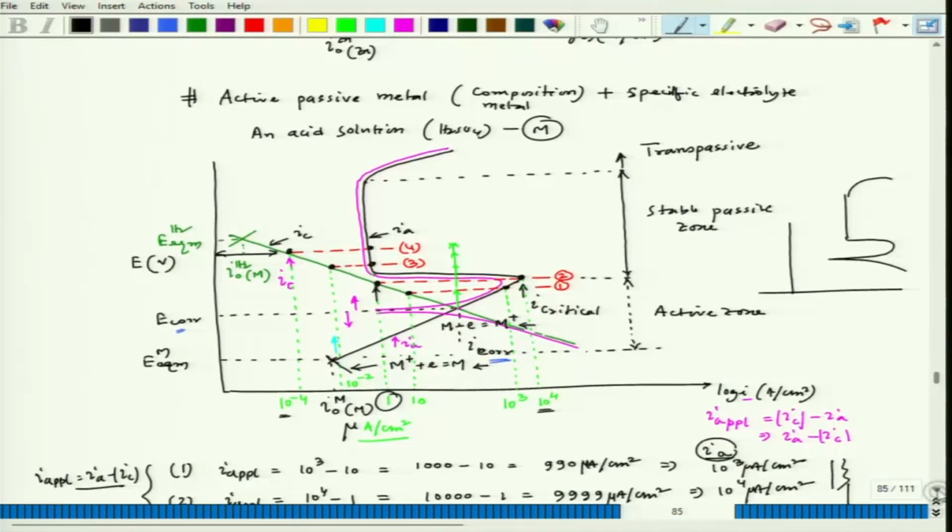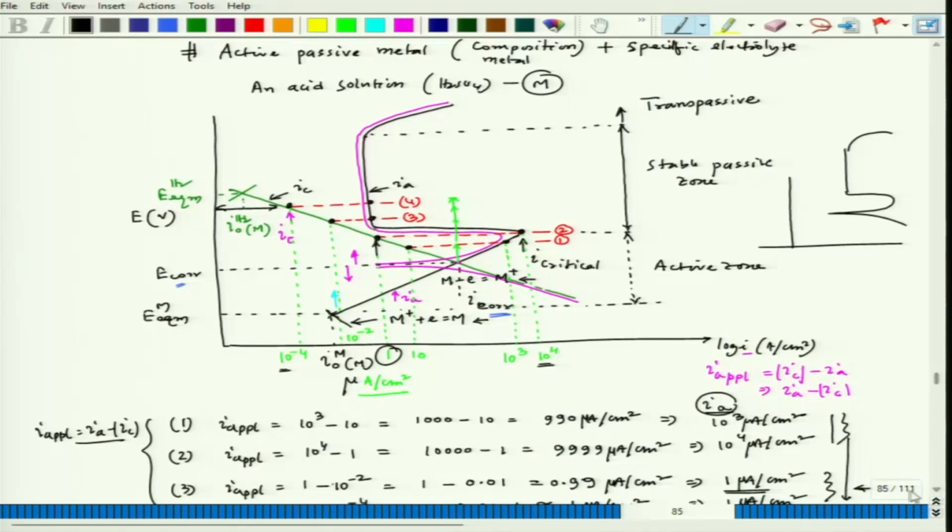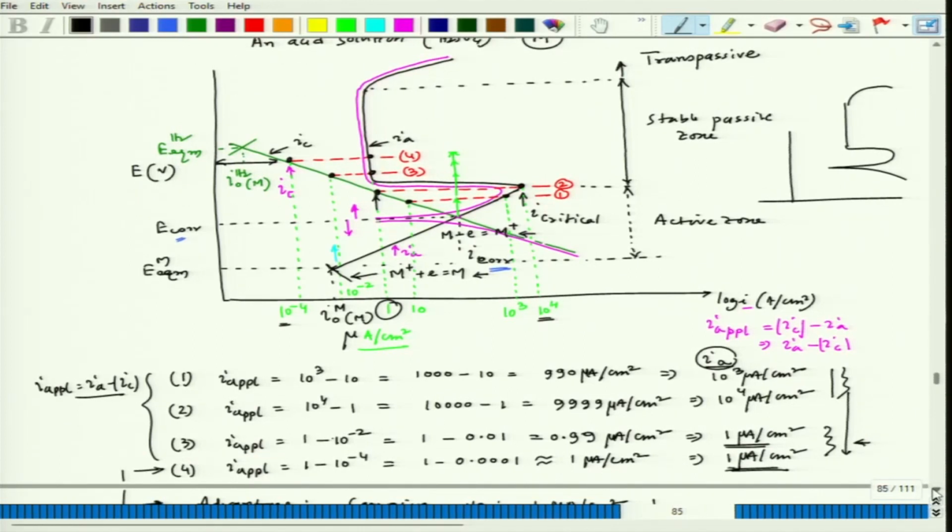But once we go to this particular situation, I can get very good corrosion protection corresponding to the passive range by maintaining the polarization at this location. So, it is better to position a bit away from the location where passivity starts, so that even if there is a little fluctuation in the current potential, it would not come back to this location.